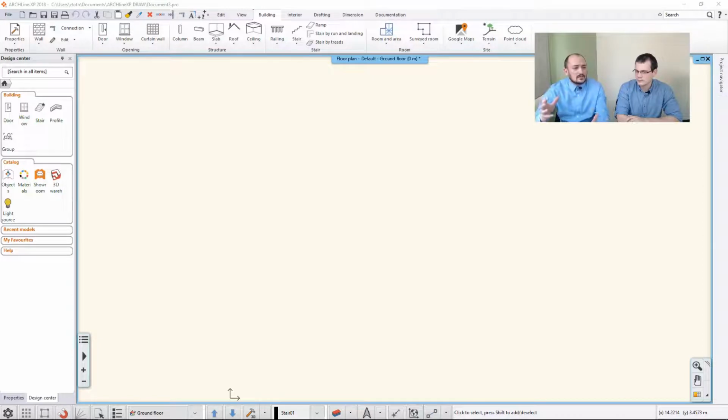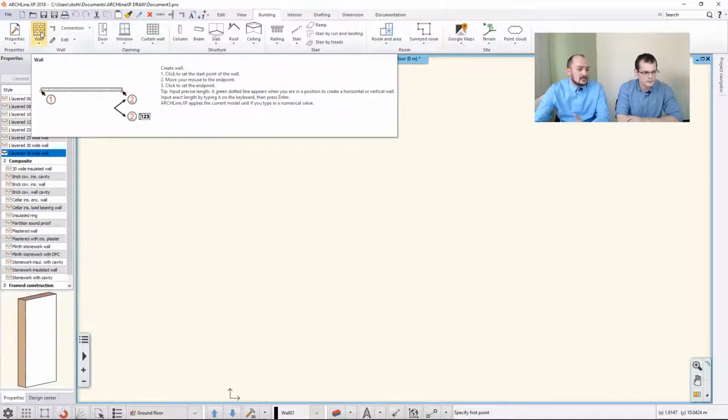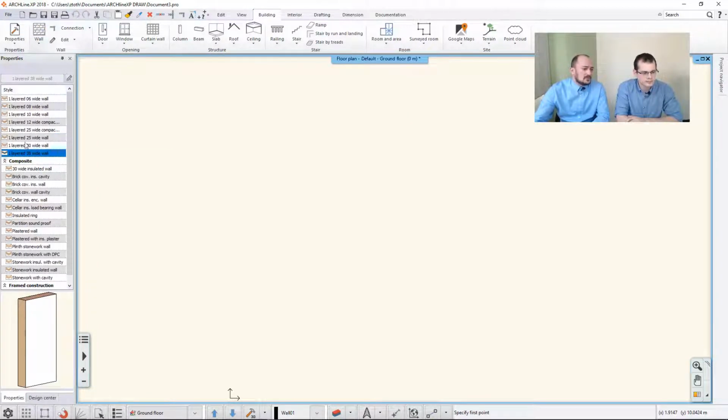You can quickly sketch the whole drawing. You can quickly sketch the room or the whole building using the wall tools, which is in the building tools. You should just highlight this and you will find the building tools. When you click on the walls, there is a whole lot of predefined sets that you can just quickly pick and use, but later at any time you can also customize them. It's worth noting that the software comes with pre-default settings for all the items, sometimes 50, 100 settings, but you don't have to stick to those.